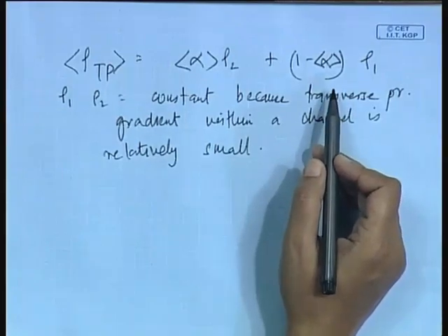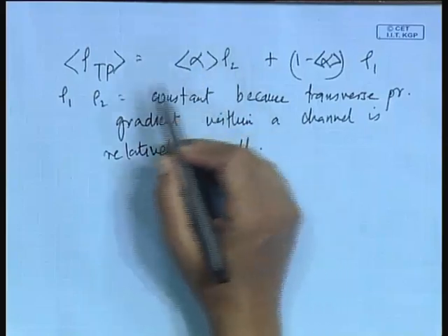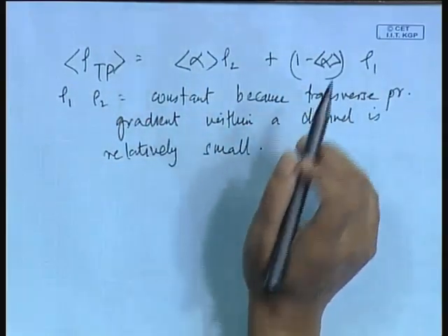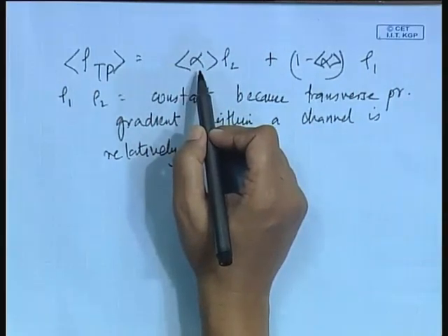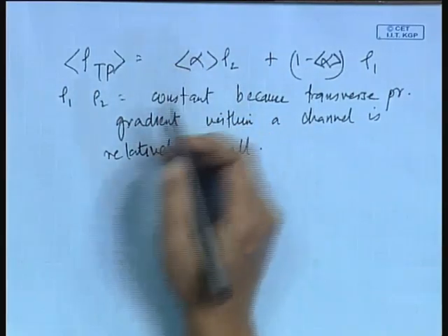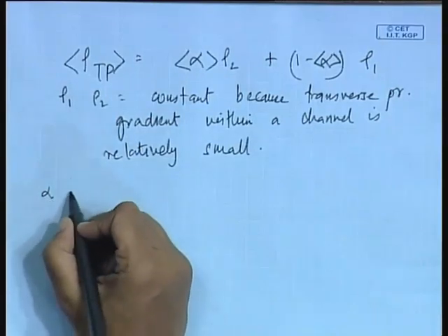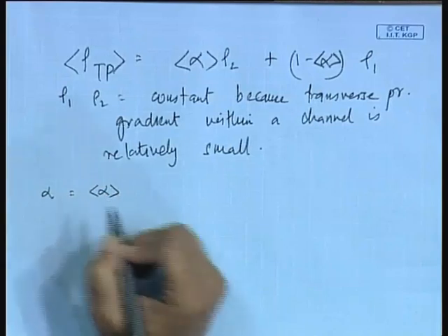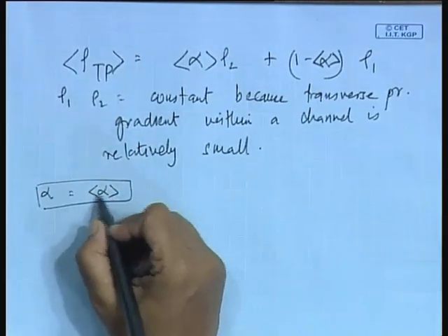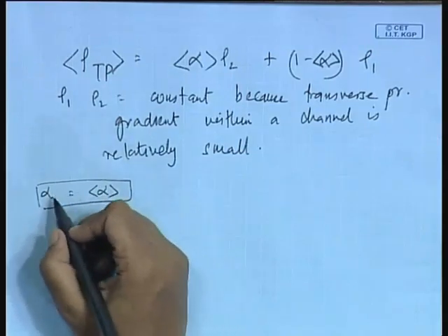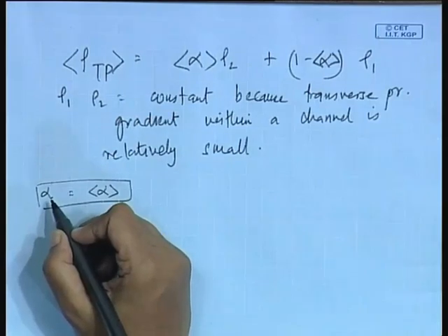Remember, after we finish the drift flux model, we will not be putting curly brackets everywhere just because it is very cumbersome, but we will imply that when we just say alpha, it is the area averaged value. It is implied that after this particular topic is over, when we write alpha, we mean this, unless otherwise stated, because every time writing this down is difficult. So, when you are just expressing it as alpha in this particular way, it is the mean averaged value.